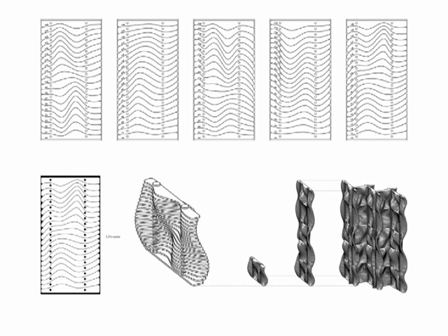Okay, so that's something that you can design into it as part of your section. And the process would look something like this basically. The tool that you're going to create is going to output a cut sheet with the dowel holes cut into it. You can't really see here, but another important thing are the labels that are on each of these things. It's very important to keep track of which one's which. You're going to have a digital model that's actually going to have labels in it that correspond to that. So you'll use the model essentially as your plan. I've been promised by Autodesk that there's going to be a day, someday soon, when we're not using two-dimensional plans anymore, where everything is done by model. Okay, this is an example of that. There are a lot of projects that are done that way. Essentially, you just open up Rhino and that's your plan. Okay, you just follow these things.